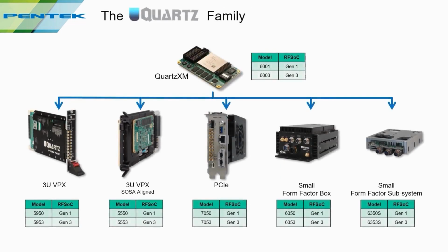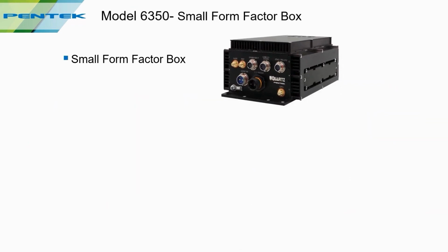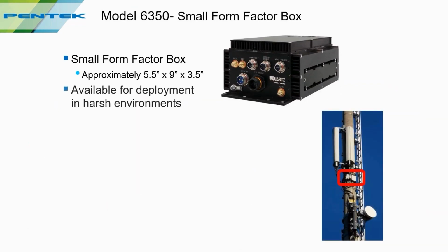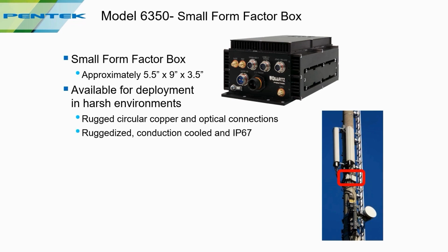Sometimes a board level solution isn't really a good fit for your application. So we also have a standalone small form factor rugged box. It's about 5.5 by 9 by 3.5 inches, and it's designed for harsh environments. So it uses military style sealed circular connectors. It's ruggedized, conduction cooled, and designed to IP67 for dust and moisture protection.